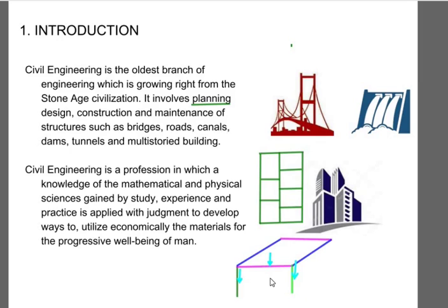So these are the structural elements: slab, beams, which are horizontal members, and the columns, which are the vertical members. The load transmission starts from the slab to the beam, the beam to the column, and then the column takes those loads to the foundation level under the ground. While transferring these loads, the structural elements also carry those loads. That's why we have to design those elements. They have to carry these loads and then transfer them.